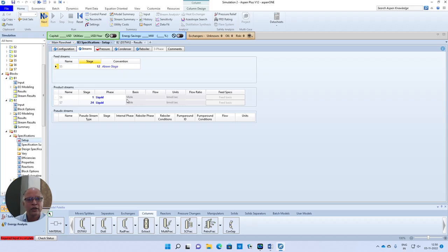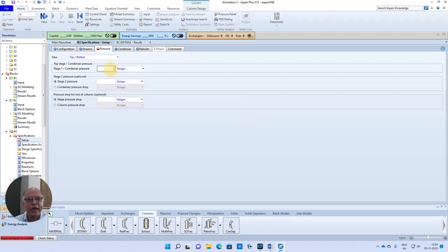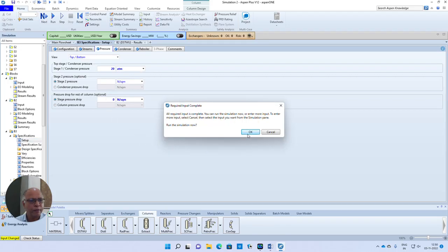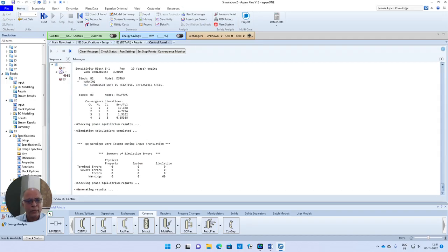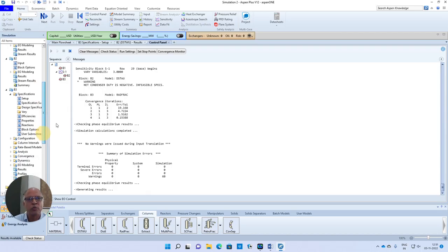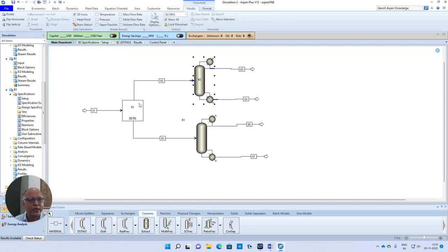So next. Though this may not be very correct, I am trying to assume constant pressure as I did with respect to the previous column. I mentioned what is the difficulty with this assumption. Anyway, go to next. So that is continuing. I should have deactivated that model. What are the results? Remember, S3 and S4 are from the shortcut design model, whereas S6 and S7 are from the rigorous distillation model.